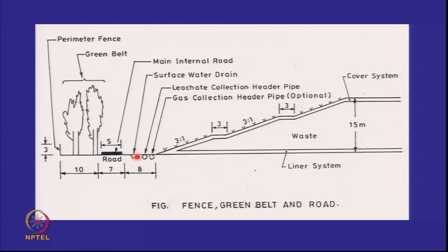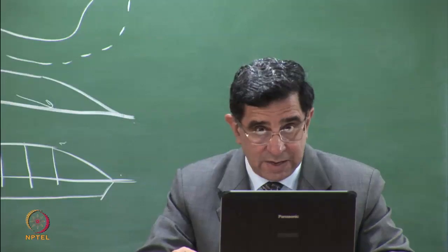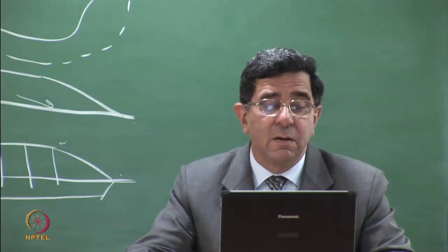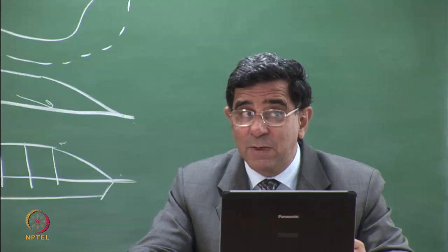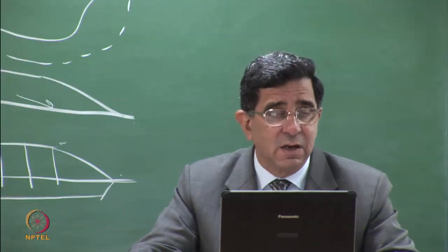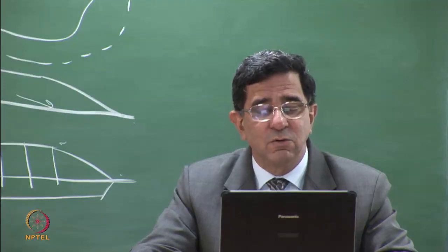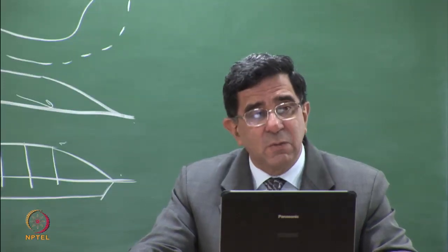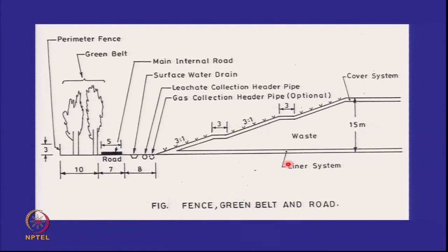And you maintain this. The good thing about open drains is they can be maintained. The good thing about pipes is they are closed, non-maintainable, unless you send in some pipe cleaning devices. But if you keep the leachate pipe open, there's an issue about odor and smell. So it's better to keep the leachate in a closed pipe and the gas in a closed pipe. So that is the way you finish off your landfill.